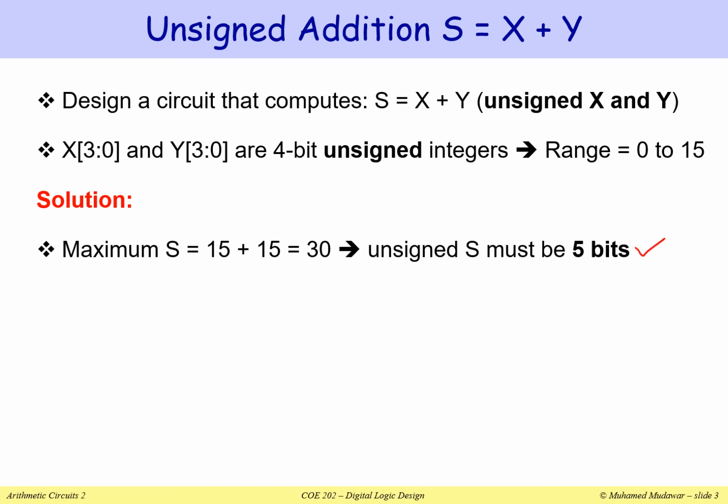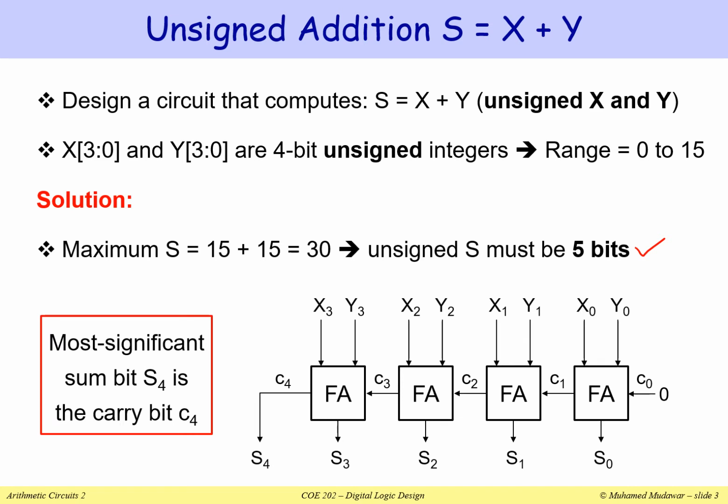You can do this with a 4-bit adder. So this is a 4-bit adder for adding x plus y. Notice that the most significant bit here, S4, is the final output carry, which is C4.